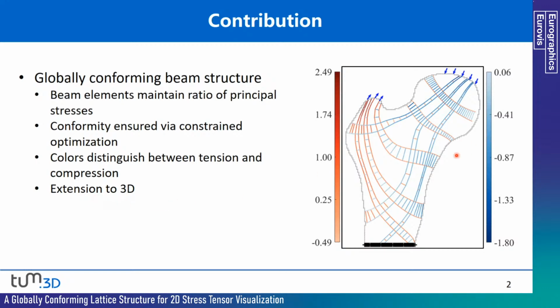This image here shows a result of our approach, where the intensity varying red and blue lines are the major and minor principal stress lines including principal stress magnitudes. The ratios of each grid cell indicate the state of local principal stresses.